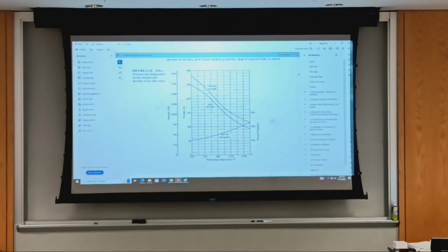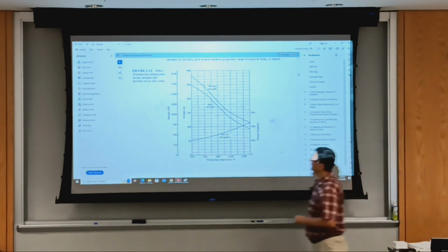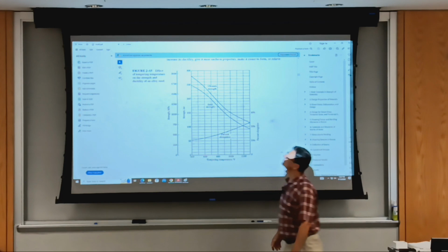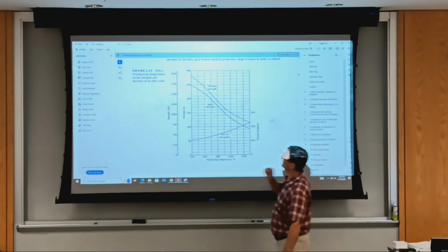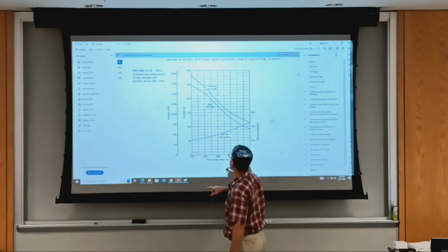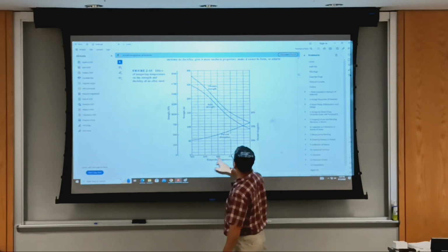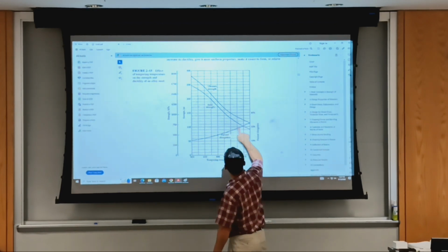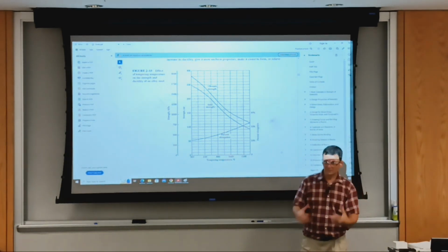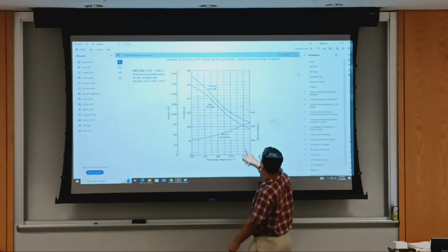This is the effective temperature, and it's for elevated temperatures, but we can have one that goes below 0. And as expected, materials soften as the temperature increases, so they become more ductile. We use this to do hot forming, forging, including.